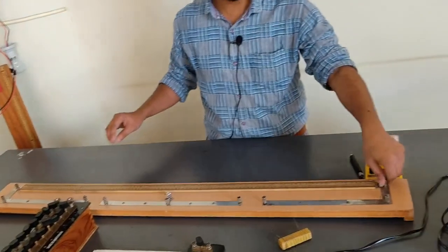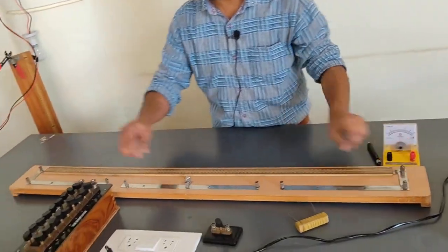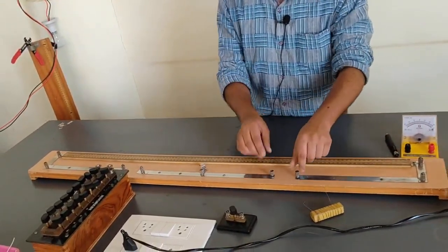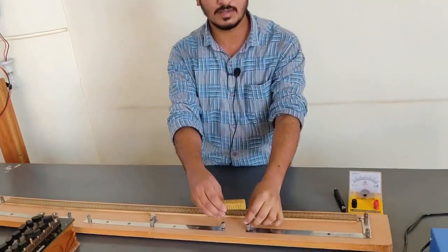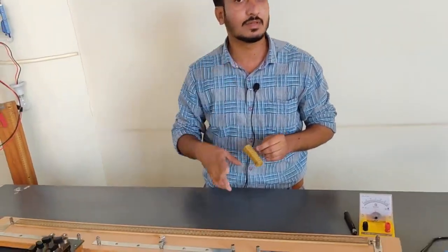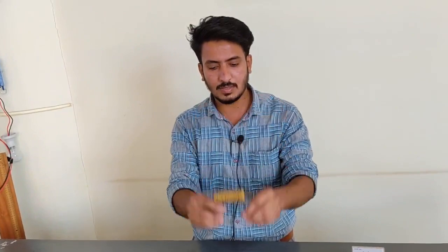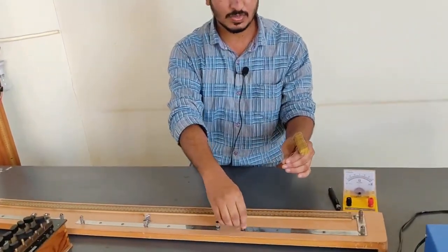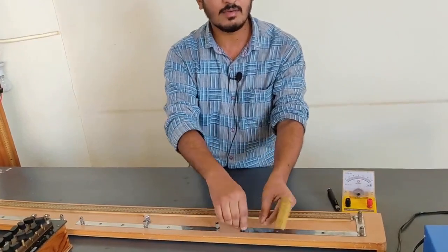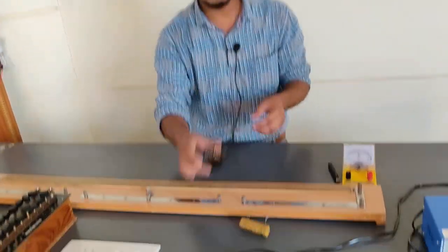This will be your A and C point, this is your B point, and this is one of the arms where the wire of unknown resistance is connected. Its resistance we don't know. From this setup we are going to calculate the resistance value. This wire of unknown resistance will be connected here. Simply we have to loosen this, tie the wire and tighten it. Then, as we know from yesterday, this is the analog key or one way switch or plug key.